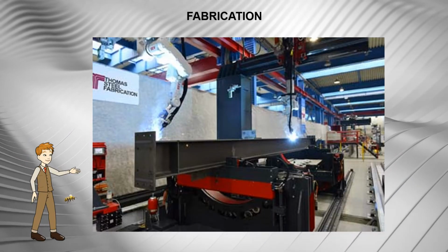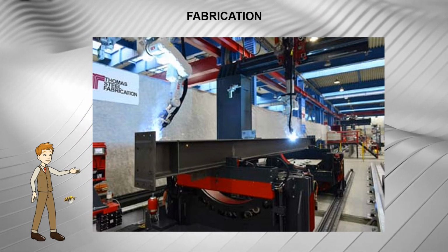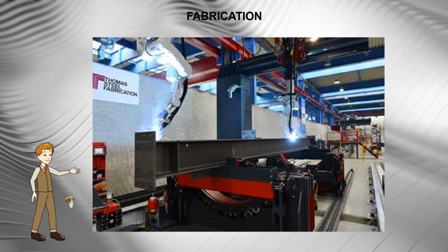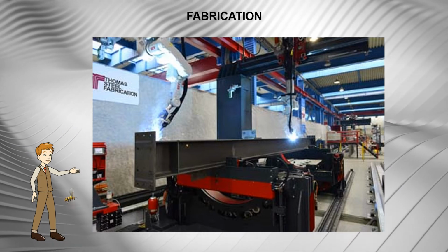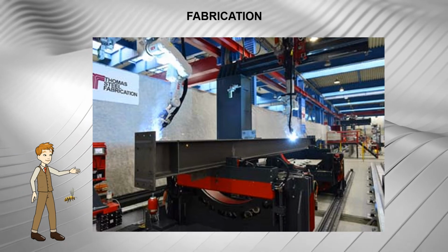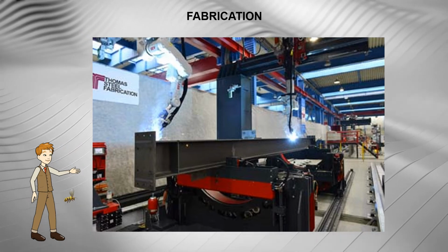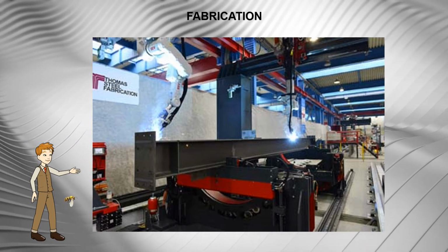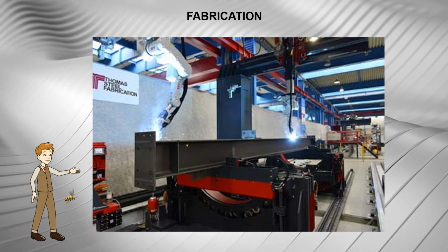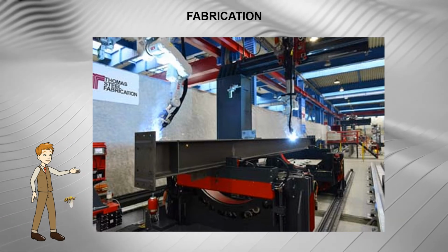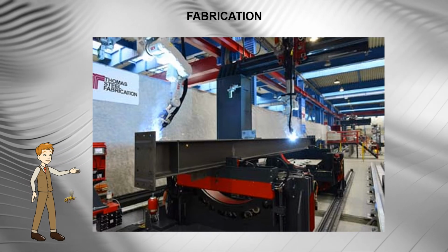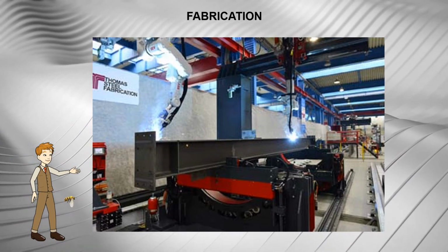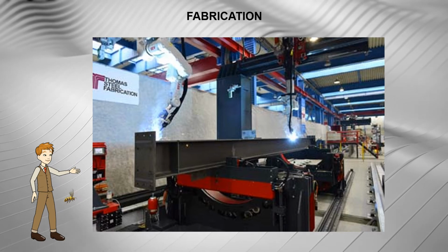Fabrication. Important factors which must be considered at the conceptual and detailing stages are the questions of workshop facilities and space and of transport between workshops and site. While large girders and or large sections may appear to be desirable in order to reduce the number of site connections, the use of large members can often reduce the number of fabricators who can tender for a given project.